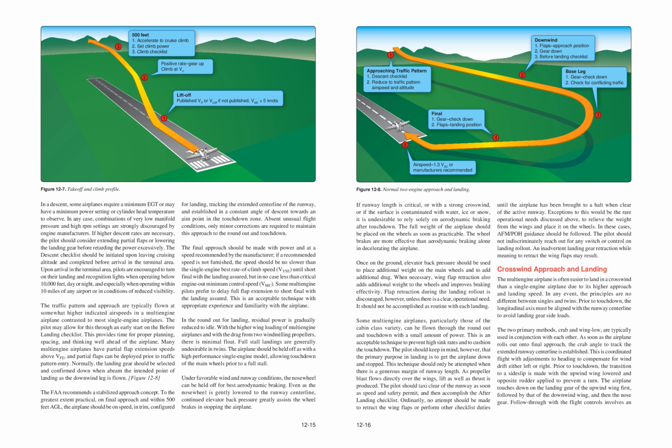The pilot should taxi clear of the runway as soon as speed and safety permit, and then accomplish the after-landing checklist. Ordinarily, no attempt should be made to retract the wing flaps or perform other checklist duties